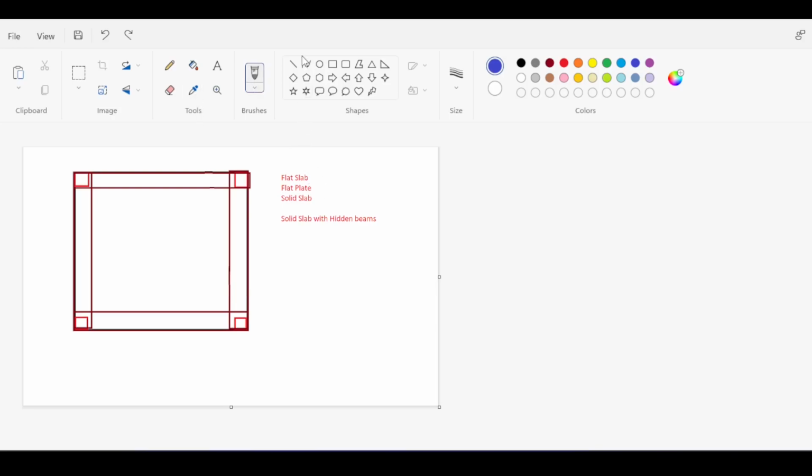This is similar to what you see in combined footings. You have a foundation like this and some people put a spine beam inverted on top of it. In that case, there is no punching shear check for the foundation, but you check the spine beam for shear. It's a long story. Maybe I will give you a foundation combined footing video later. I know I didn't touch on that. There are so many things I can talk about over it. This is really nice and really juicy.